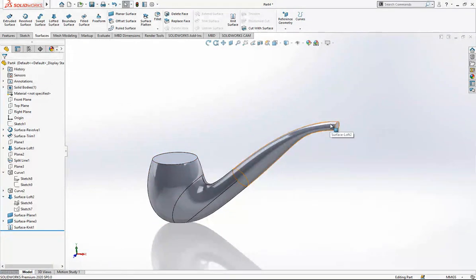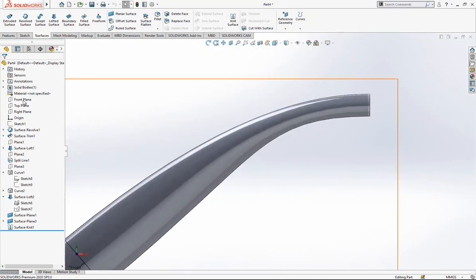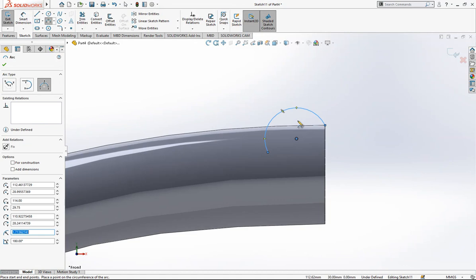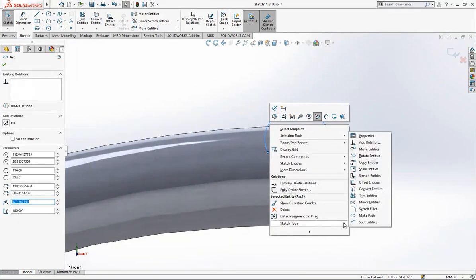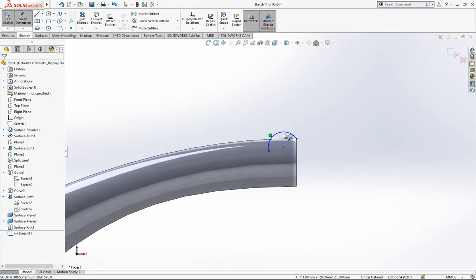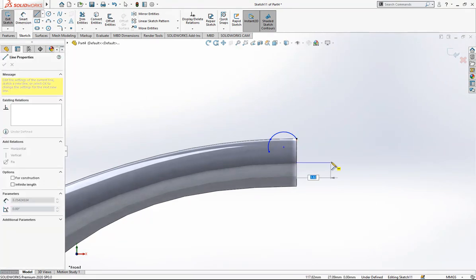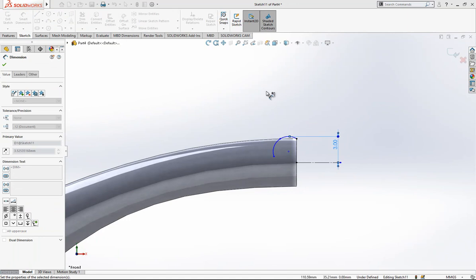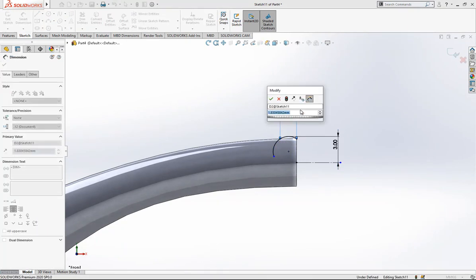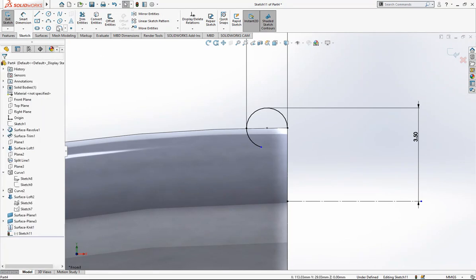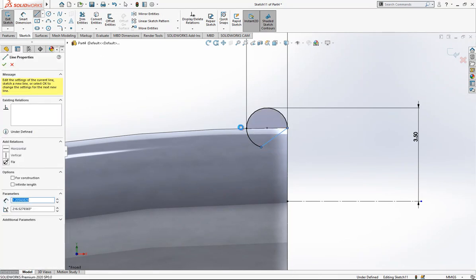We should cut our profile and finish the detail here. First, let's finish the detail where you put your mouth. Here I place a circle, and I right click there and split entities. And I split this entity to be able to put extra construction geometry here where I can give the value. 3 is good. And here 1.5. Oh, 3.5 would be, sorry. I extend this part to penetrate when we are making a sweep operation.